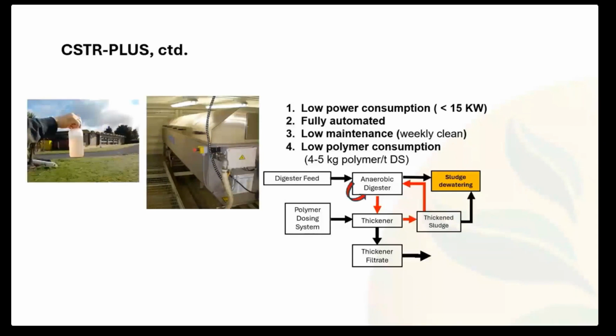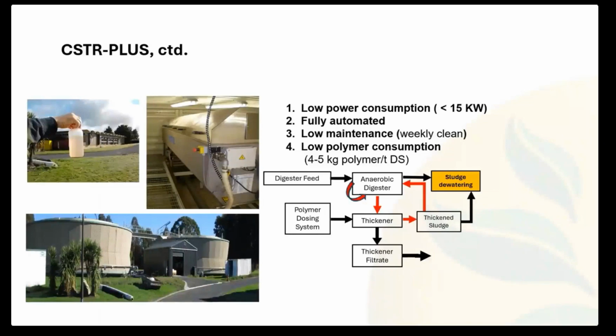Here, an example of the filtrate removed from a municipal wastewater treatment digester. In this application, the recuperative thickener was in a separate building and allowed basically to run the whole sludge load in a single tank, permitting the clean out and rebuilding and optimization of digestion in the other tank. And then one could basically swap over the thickener to the reconfigured tank and also upgrade the tank that was before running at double the load due to the recuperative thickening or the plus configuration.